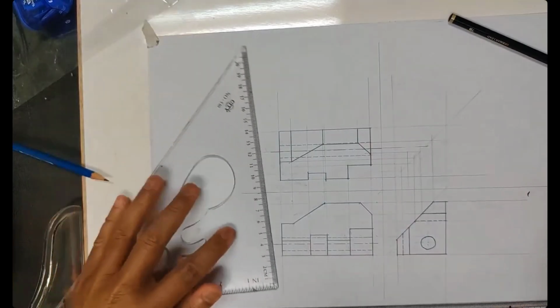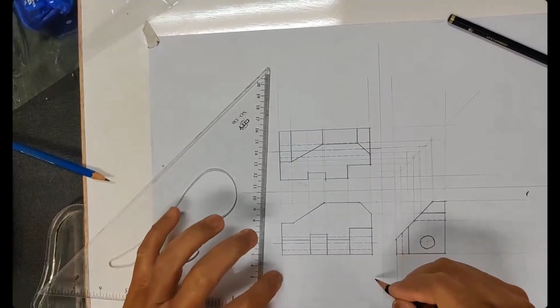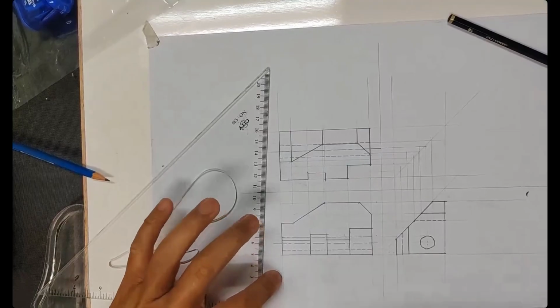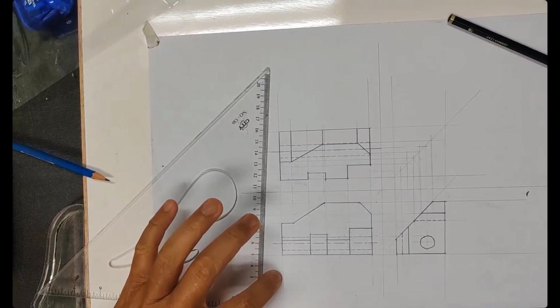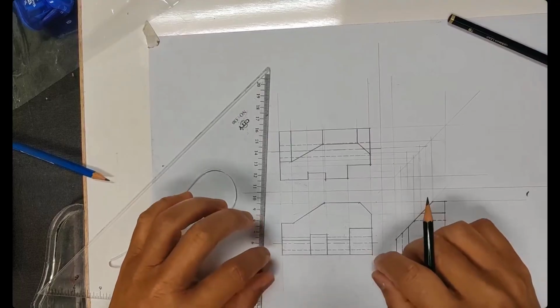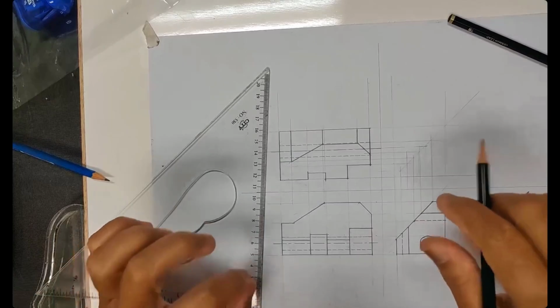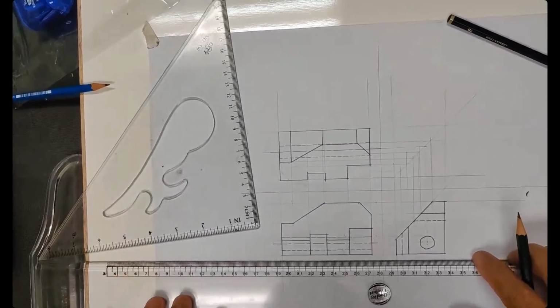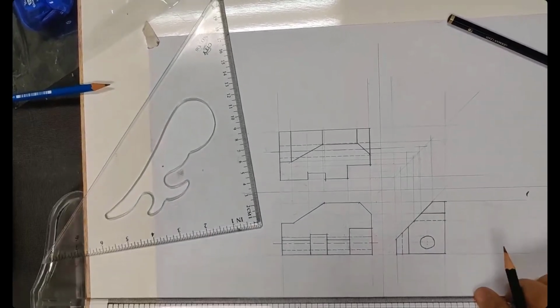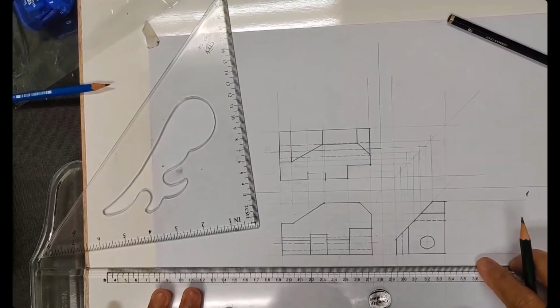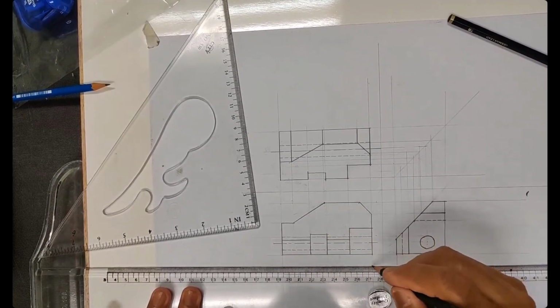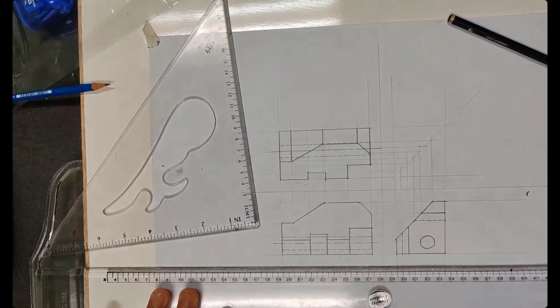Okay, but if I put 80 here, I put extension line. You have to obey the rules to do dimension because it's a standard practice. Remember, letter height of dimension type is 3 millimeter. Do not put your dimension too close to the object and not too far away. So it's about at least 2 letter height. But I cannot make the total length at the first level because I have a length of 25, I have a length of 15 of the cutout. That one has to be inside first.